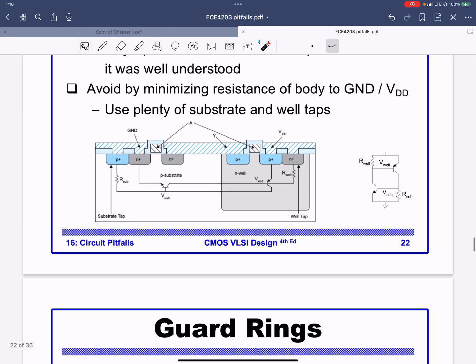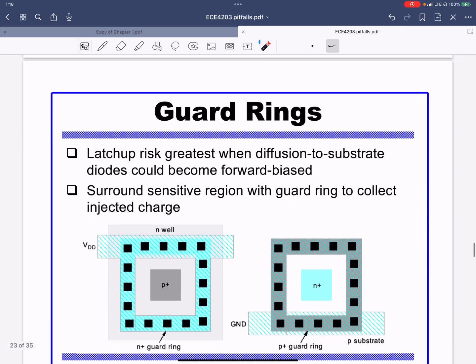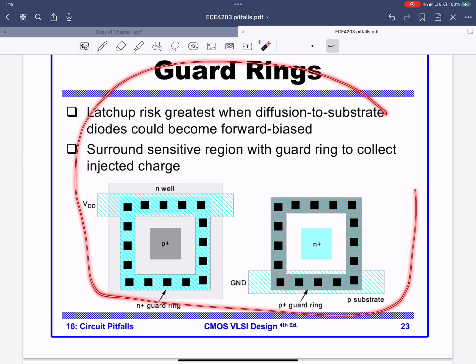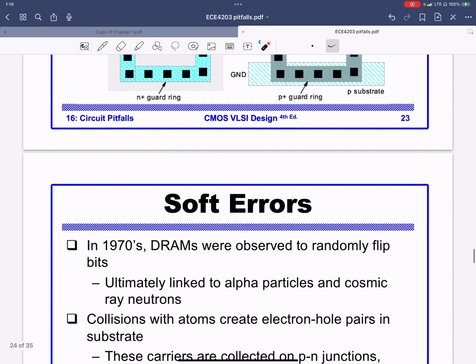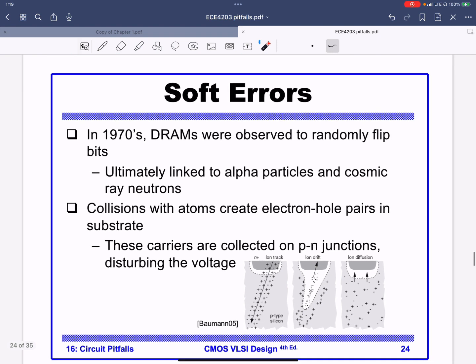These days, you see them more possibly in the peripheral circuitry, in the I/O pads themselves, and really the way to get around these, I think you might have seen it when we were talking about input-output pad discussions, where we had guard rings placed around the P and the NMOS to prevent this from happening. So those are those permanent errors.